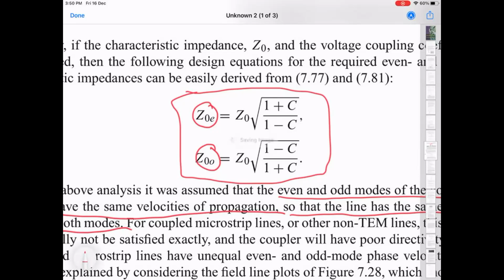Right. And I think part of the confusion in thinking about that is that with this even-odd mode analysis, we actually always are considering only one half of the mirror image picture, right? But the even mode involves both the transmission lines. They're doing the same thing, but they're not doing the same thing when they're far away. Sorry, that's sounding really strange. But as they come together, this mode's capacitance, the combined capacitance, starts to get affected because of the interstrip capacitance as well. So whatever C you choose, you always have to satisfy this, right?